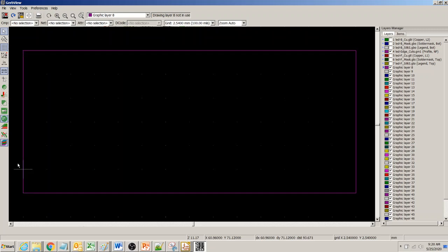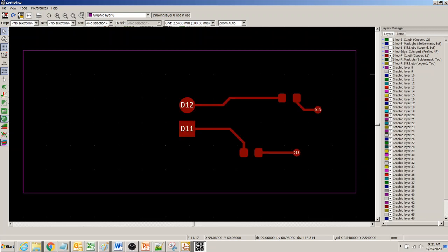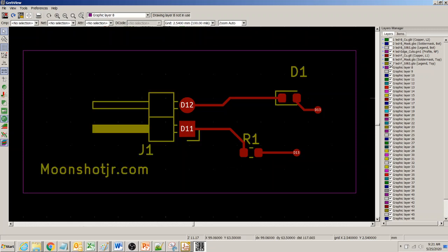We unselect all of them and then start selecting one by one, starting with my cutout, which is right here, and I see that my cutout is looking the way I wanted it. Next I can turn on my top layer, this copper layer on the top side, which is looking good to me, and then I turn on the top layer silk screen. These are also aligning as well. Just make sure you have anything else that you want to include. If it's not there, you may go back and check that layer and fix it and come back again to generate that Gerber.